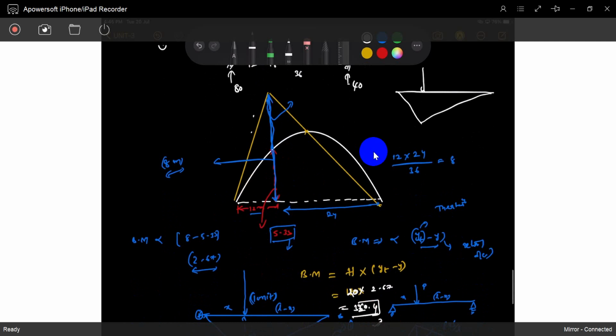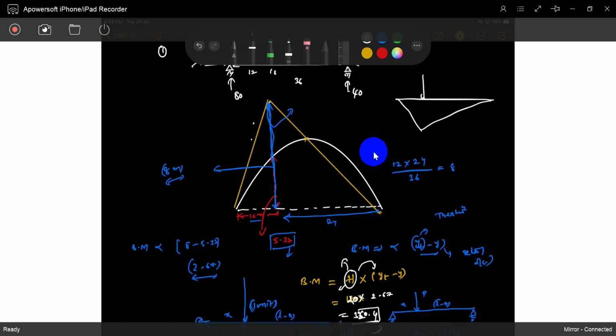The bending moment is the horizontal reaction multiplied by this, na? So if you apply different loading, the H will change. So no problem at all. The effect is included in the H. So for this theoretical arch, the vertical intercept is taken for just one unit load.